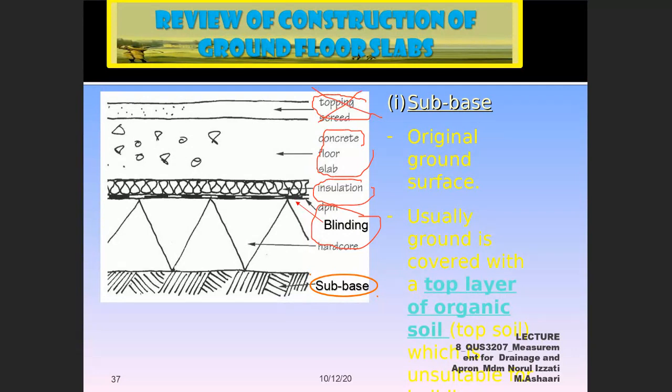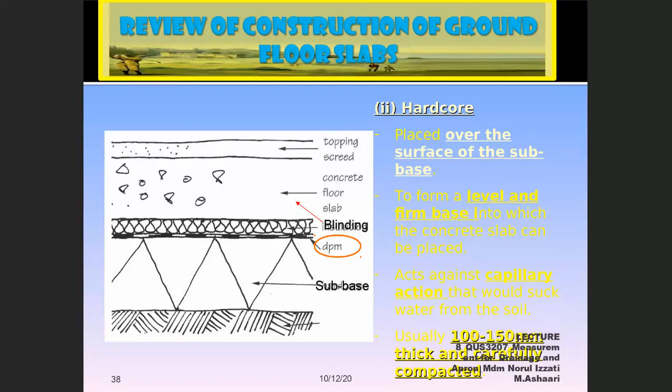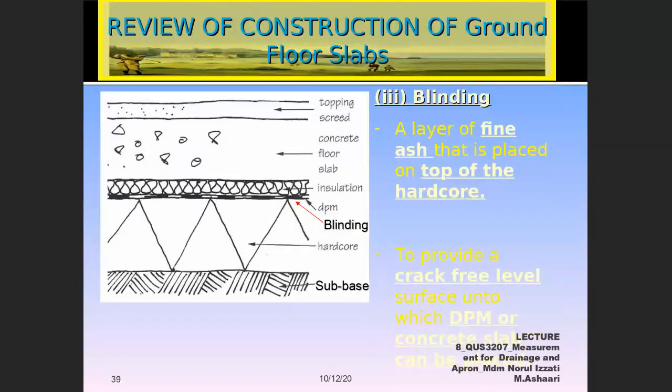external floor finishes. If you need to measure, you only have to measure from the hardcore and the concrete work. And if you have any DPM or insulation, depending on the detail, then you have to measure. This is only to show you the recap of the components that you have to measure, if any.